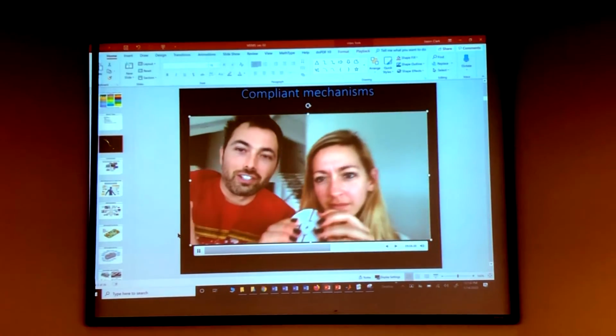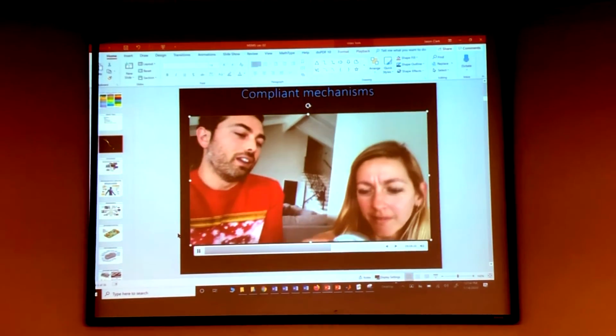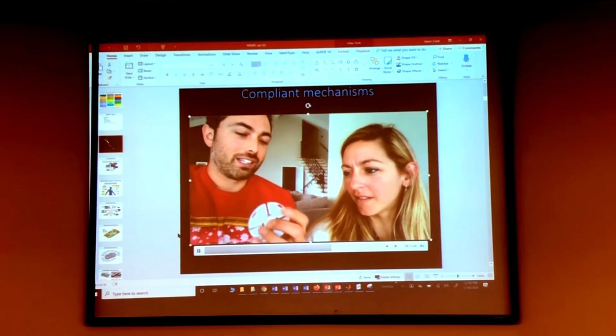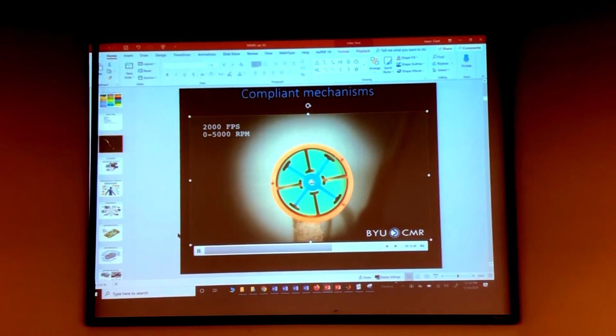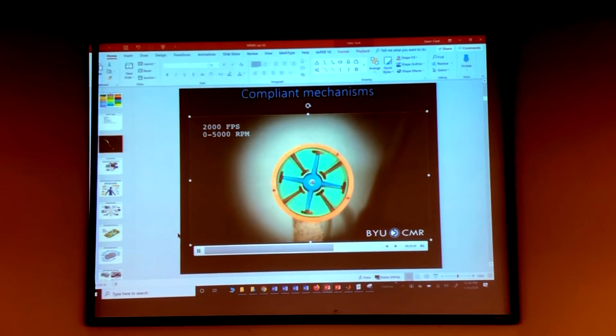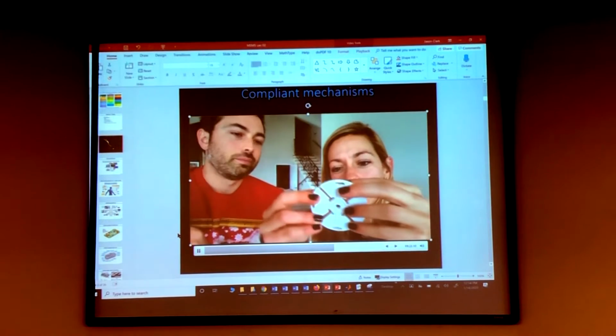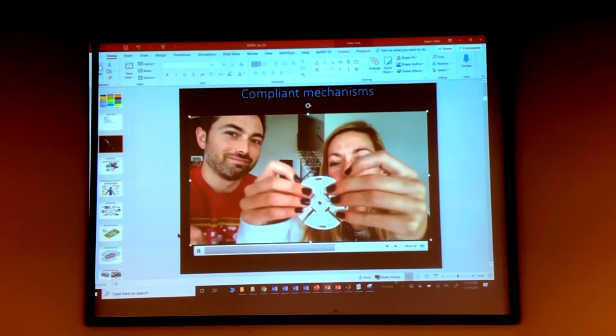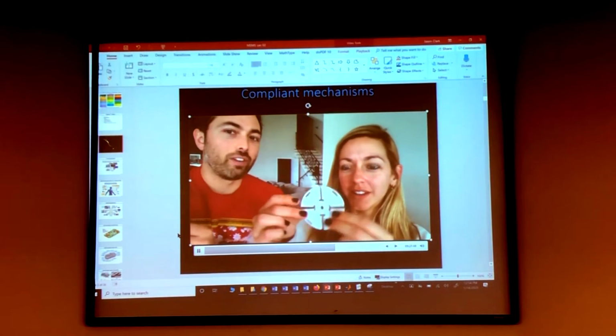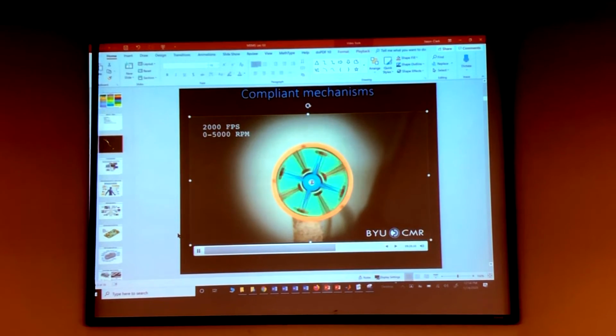Okay, that is a clutch. So the idea is, if you spin it up really fast, because it's flexible, this outer part will actually start coming outwards. And then if there's a drum around it, it'll contact with that drum and spin that thing. Oh, so that kind of comes out like so, and it then gets spinning really fast, and then you essentially engage this outer drum. So this is like the way that a chainsaw would work or something like that, because you get it spinning fast enough, and then it engages the chain, and then it turns it over.